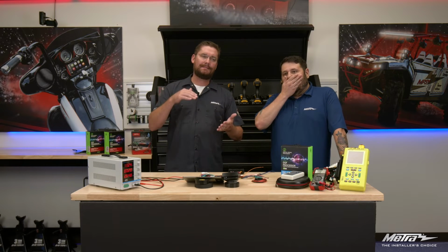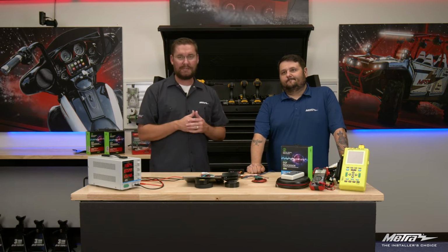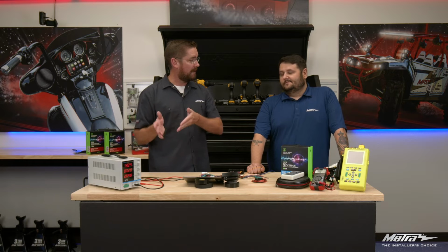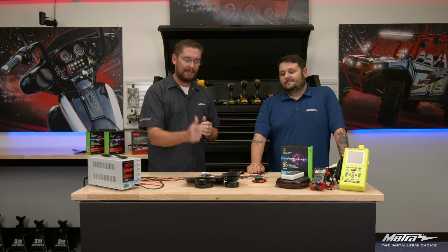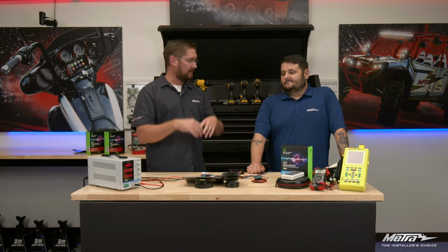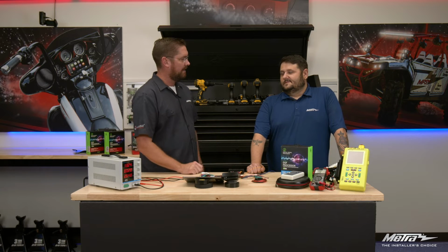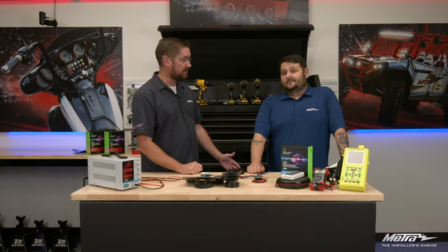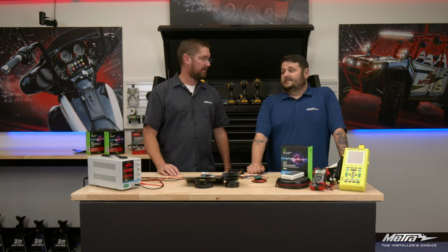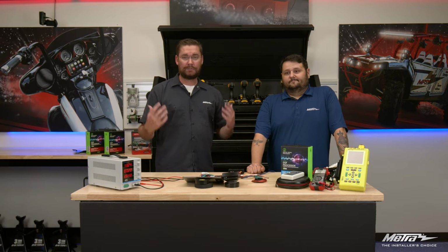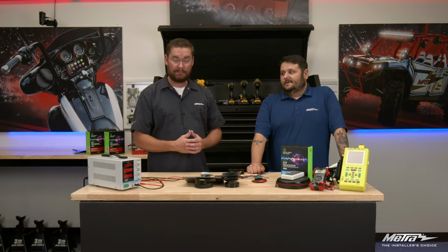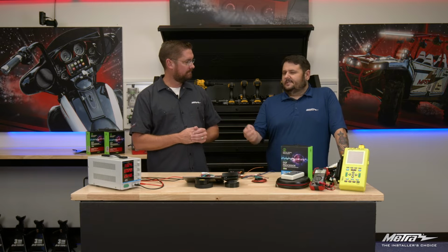And what lockdown does is it saves any changes to the DSP. So let's say that we went ahead and selected the Avalanche with a factory amplifier, but we didn't lock it down. Well, we're going to shut the app off, do all of our settings, shut the app off, and shut the car off. It's going to sound great until you shut the car off. And when you cycle the ignition, oh no, I've got no sound. It's going to lose its mind when it comes back on. No sound. Where'd my chime go? Yep, where'd your chime go? So there are issues that arise because you haven't locked it down and saved the information. Lockdown is your checkpoint, if you will.